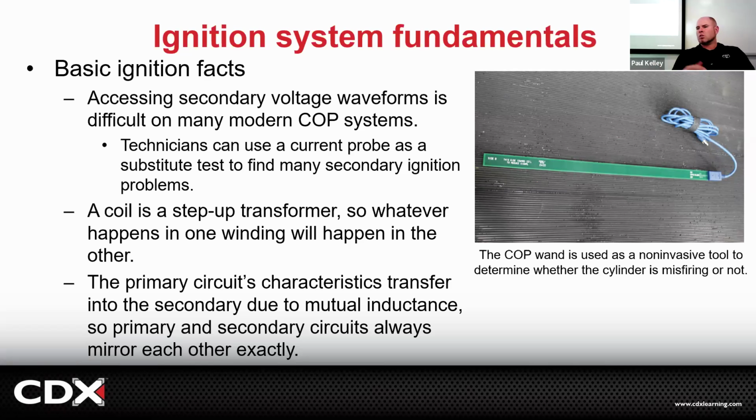No, a misfire, at least, no spark. Yeah, if you got that on all the coils, then yes, exactly. It depends on the system, but the point is, if you have low voltage making it to the primary because you have a primary wire chewed, guess what? You got low voltage on the secondary, not sparking the spark plug. Make sense? So when she sent me the picture of the primary wires chewed, and I knew that the code was for a primary circuit, it's like, duh, fix the primary.